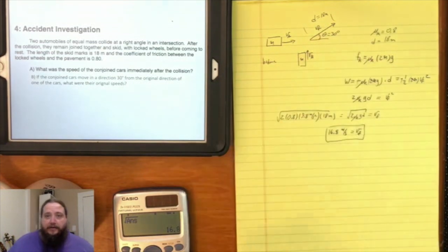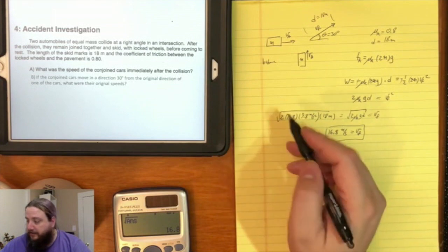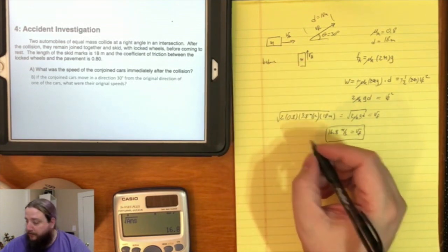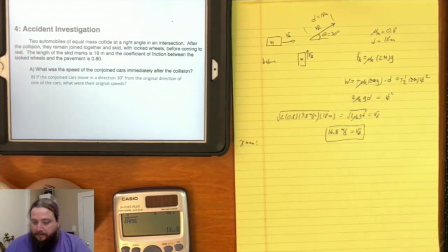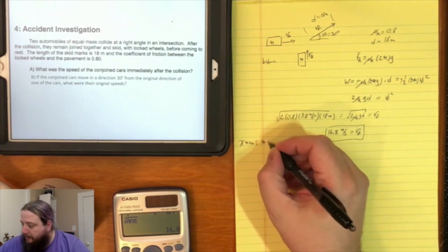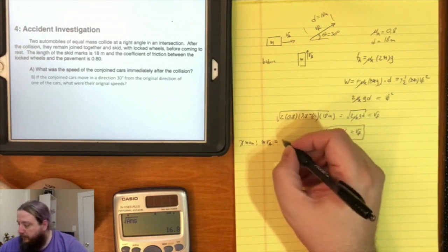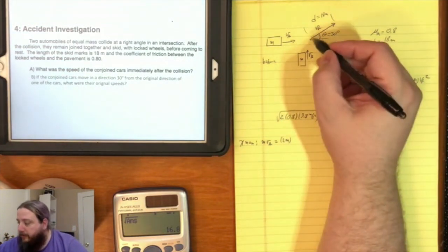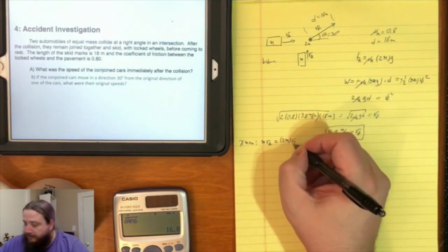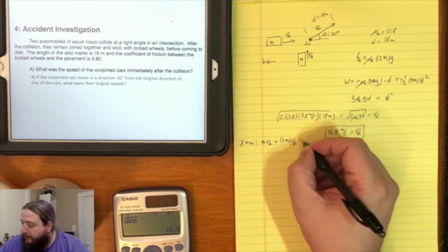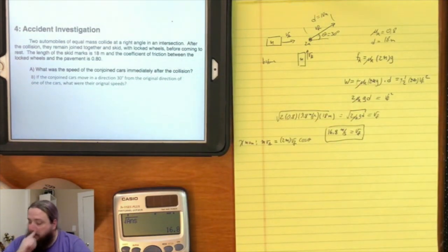If this angle here is 30 degrees, then we can use momentum conservation. The horizontal, or x, momentum conservation is going to look like m times vA is equal to 2m, because we have an object of 2m moving at velocity vf, but it's only the cosine theta, so the x component of that.